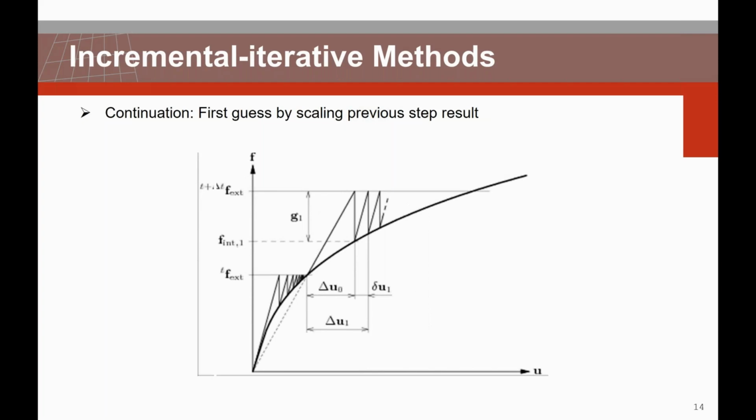If a deformation process is relatively continuous, then the displacement of the previous increment can be used as a first prediction for the current increment. The displacements are scaled by the ratio between the current and the previous loading factor, or by the ratio of time increments in case of time stepping.